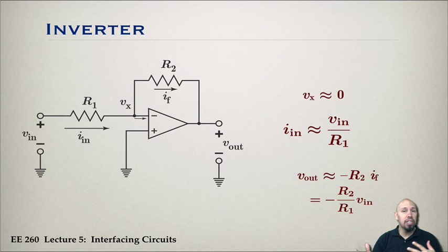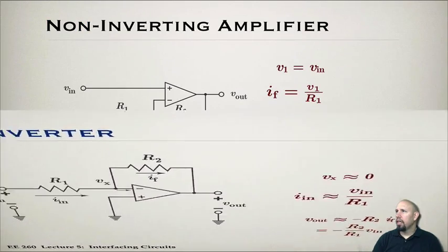And there may be good reasons for doing one or the other. Okay, so what this tells us is how to do that. By appropriate choice of those resistors, R1 and R2, we can get various gain levels. So that's very helpful in being able to get a meaningful voltage out of here. Okay, so this is a good thing, the inverter.